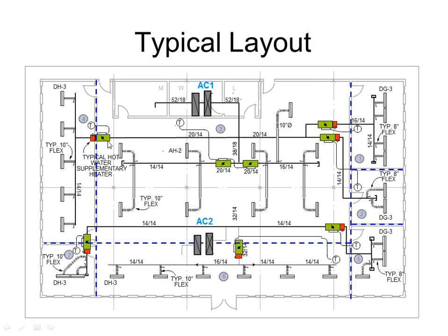The reason we have supplementary heat on this system is because we have an east and west exposure. During the morning, obviously, the sun rises on the southeast and then sets on the southwest. In the morning, if you have a high heat load from the sun on this east exposure, you're going to put this unit into cooling mode. The problem is you're not going to have any heat exposure on the west side during the morning, so you're going to require heating because you have outdoor windows probably that are affecting the zone, cooling it off.